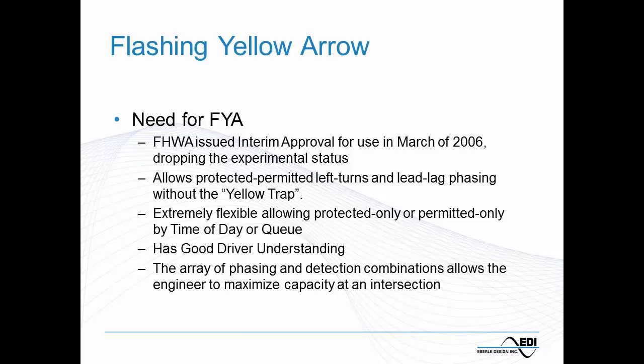The yellow trap has been a hang-up on protected permissive left turns, and we have several different examples over the years of schemes, louvers, and so forth to try and prevent it. It's an extremely flexible tool for the traffic engineer. While it's a surprise to many drivers as we deploy it, once they see it and experience it, and with some minimal level of signage, it appears to have good driver understanding. So this is a great tool for the traffic engineer.